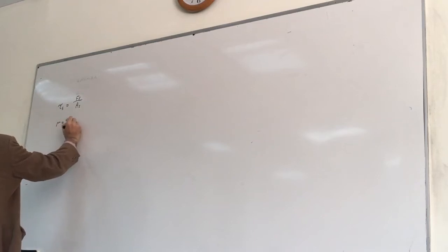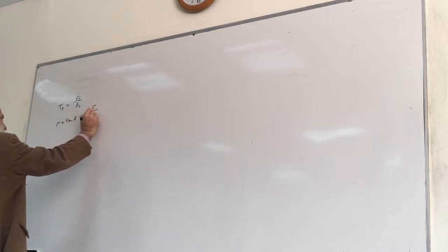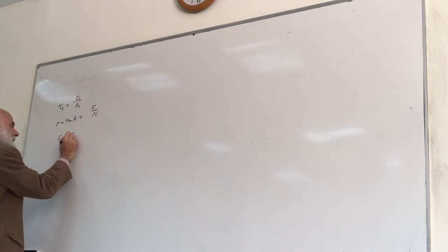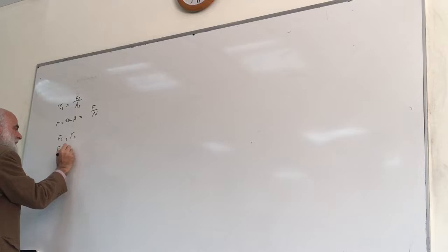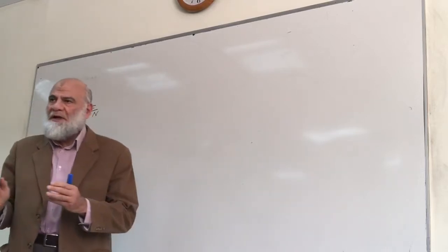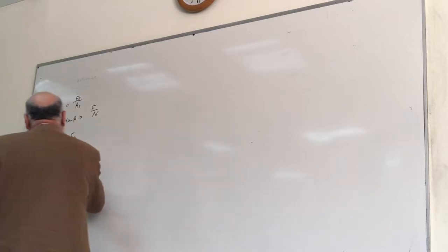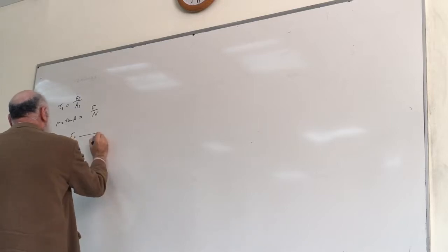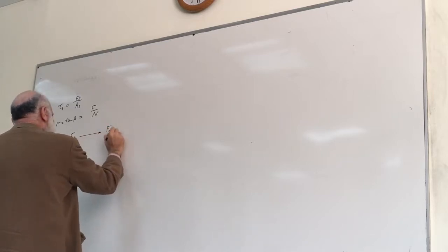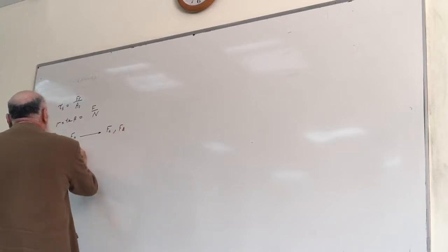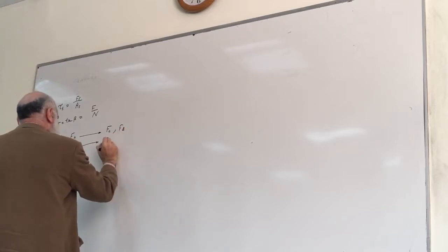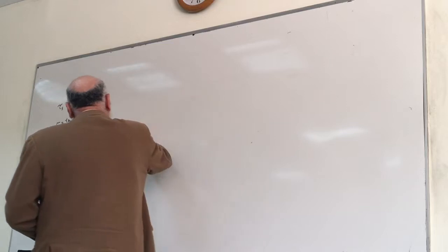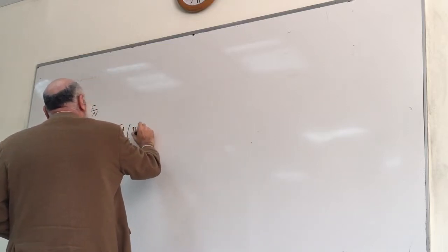Tan beta equals F divided by capital N, and Fn with capital F and capital N. Both are components resulting from the FA and the FC. Now we can get these two components from FC and FA, and we can get these two components also from FC and FA, where we measure them both by dynamometer.